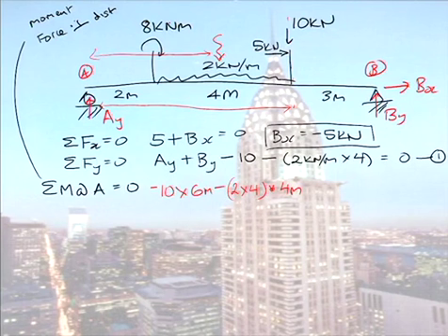It's going clockwise, so we would just subtract 8 as is, because it is already a moment. And then finally, we have our 5 kilonewton. Now, this 5 kilonewton causes a moment too, because when I follow the arrow line back, it does not pass through A. A is down here, and this is the line of my 5 kilonewton force.